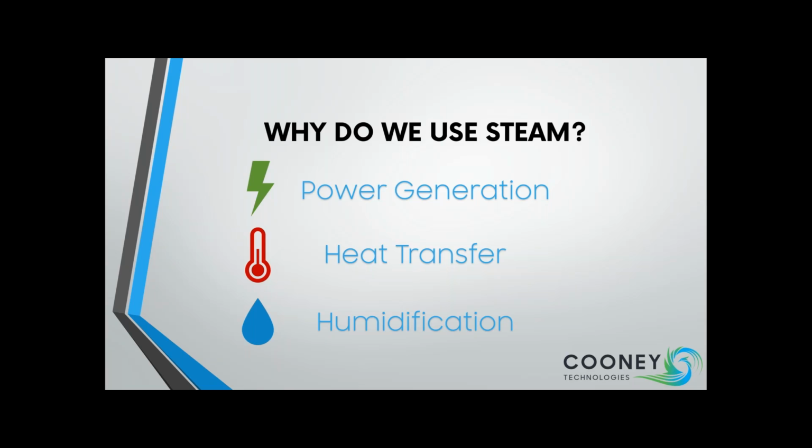Steam is used most importantly to us as a heat source for heat transfer. And this is where it holds a special place in my heart. It can be used inside steam preheat coils in an HVAC world because it can heat the incoming frigid outside air, and used in various types of heat exchangers also. All these heat exchangers can generate domestic potable hot water or heating hot water or a variety of other hot process fluids or slurries. Steam tracing is another example where steam is used for heat transfer.